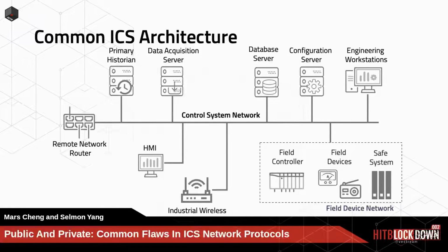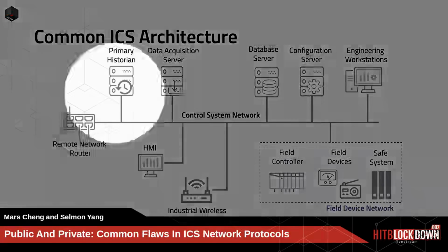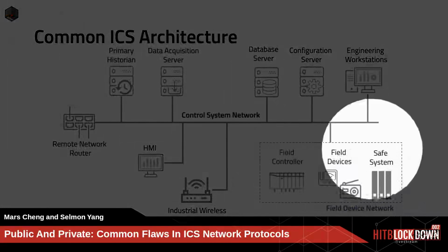One is touch panel, like we see in this picture, and the other is software based, which we usually load onto a Windows computer. The HMI provides a graphical representation of the process for the operator, and it can be used for control, monitoring, learning, and training. Field devices are things such as meters for pressure, temperature, liquid flow, gas flow, and so on. Different types of factories will use different field devices.